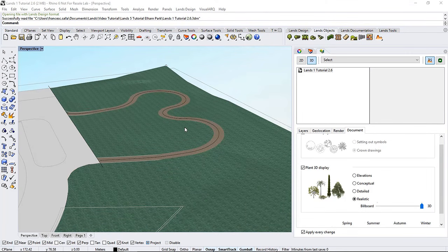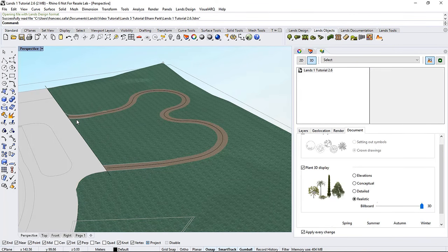In this last part, we will learn how to add a subdivision object in an area of the terrain. We've added them previously when creating paths, cut-in fills, or holes on the terrain. In this case, we will use the command to create an individual subdivision object that defines a part of the terrain.